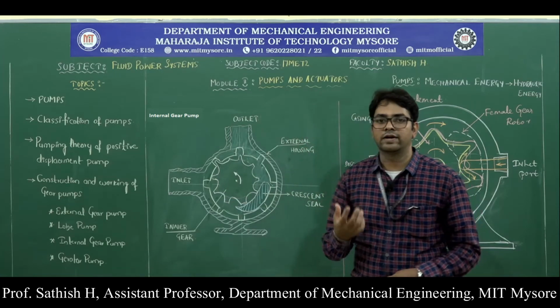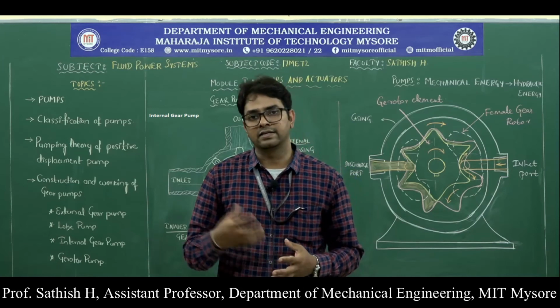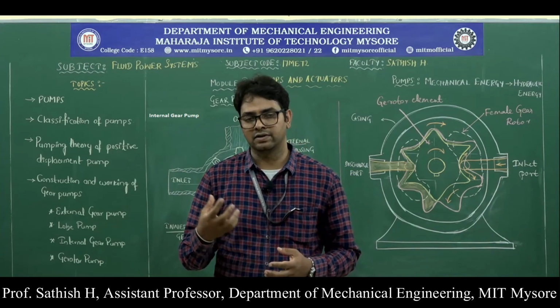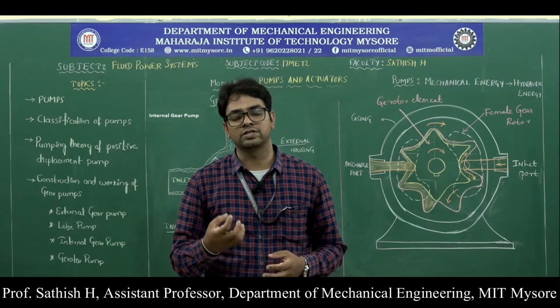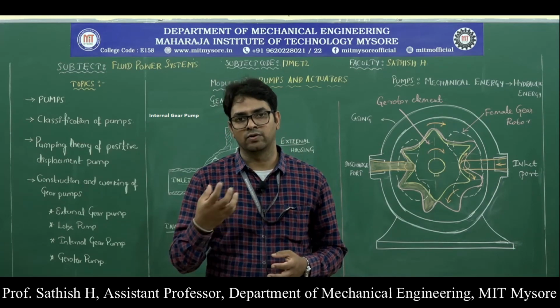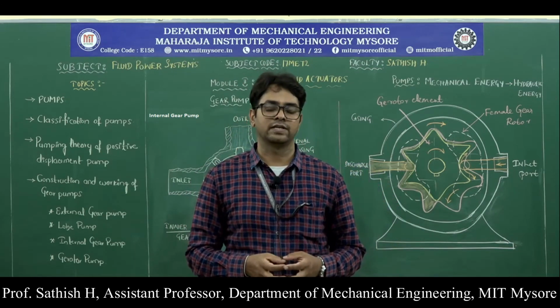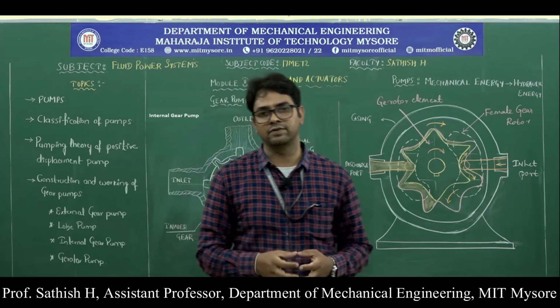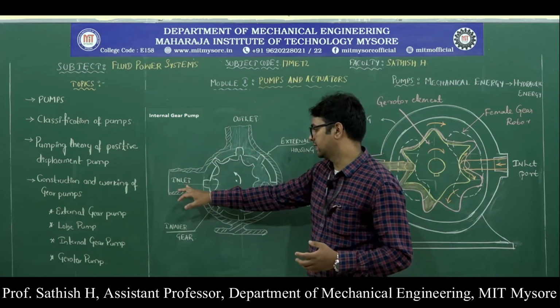Coming to the working principle, as I said before, in the case of the pump, due to the mechanical action, one of the gears is driven by the prime mover, because of which a vacuum is created. The hydraulic fluid inside the tank, which is at atmospheric pressure, is drawn to the inlet of the pump due to this difference in pressure. So this is the inlet.